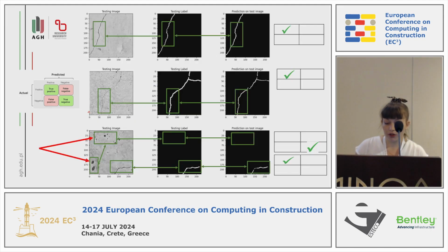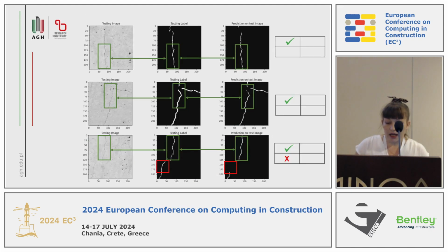And going to the results of our network, this slide shows the results corresponding to true positive and false negative, which give satisfactory results. The next true positive results also include more challenging images, which are more difficult cases, and automatically performed feature engineering gives different results because the network detects cracks regardless of direction. It does not learn only a single pattern, for example, a vertical crack.